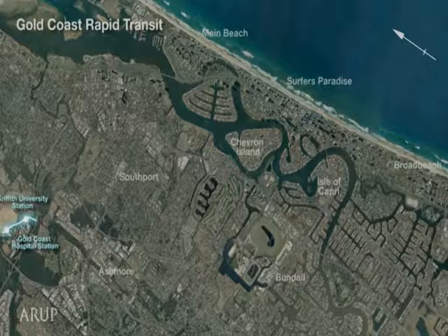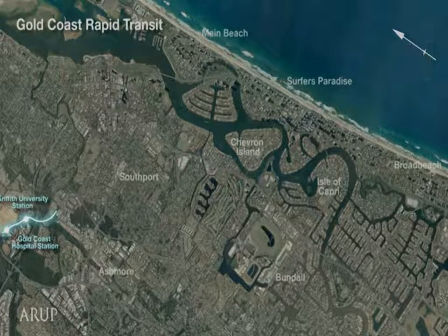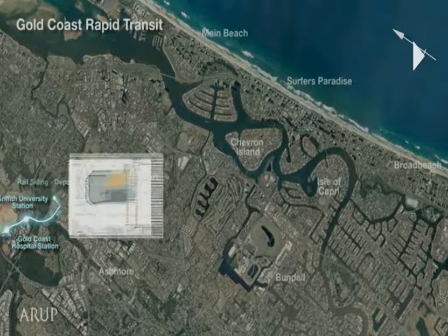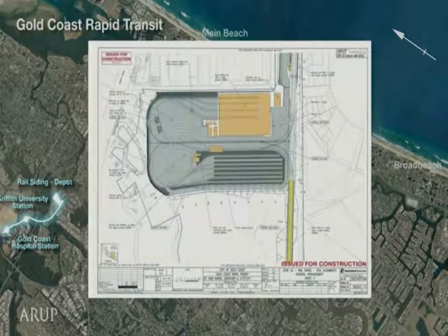Griffith University Station is one of the 4 LRV stations that has a bus interchange connectivity type thing. Okay. After Griffith Uni Station, the rail alignment lifts up onto a 400-metre viaduct. This viaduct spans the Smith Street motorway and also spans a fairly significant environmental section of the Gold Coast. From here, the viaduct lands on a piled track slab and access to the LRV depot. Hinson will give you a bit more about that.